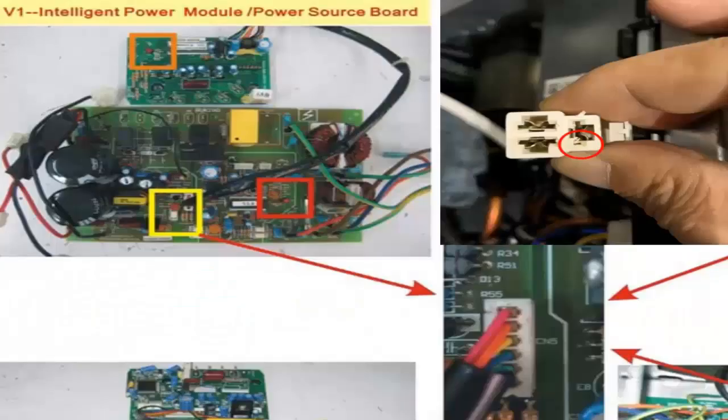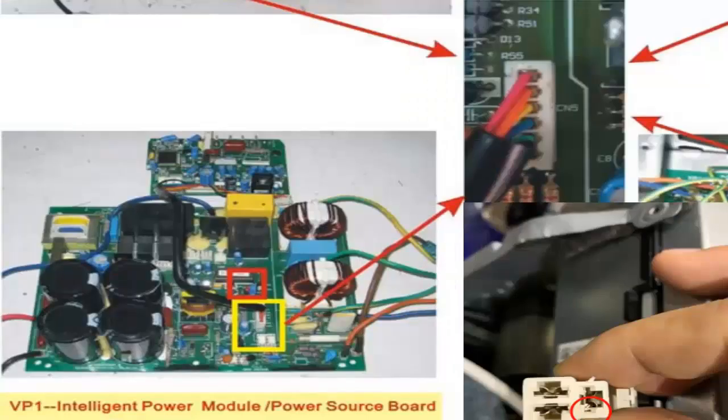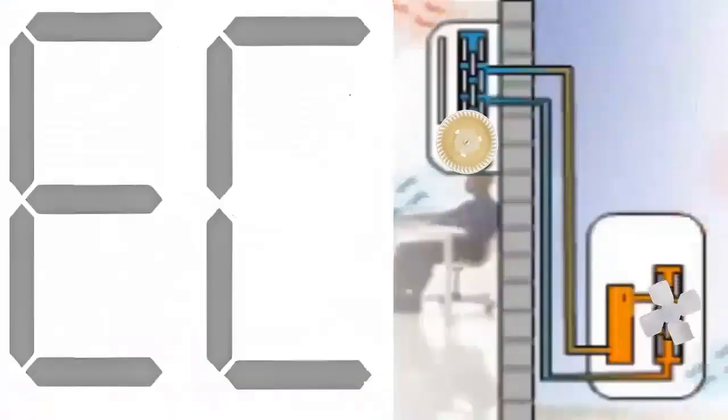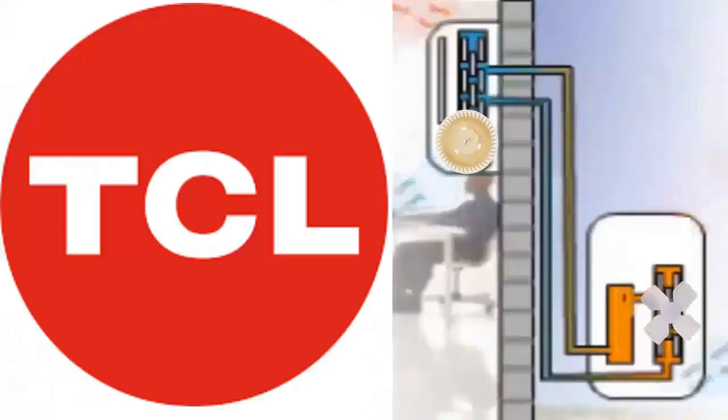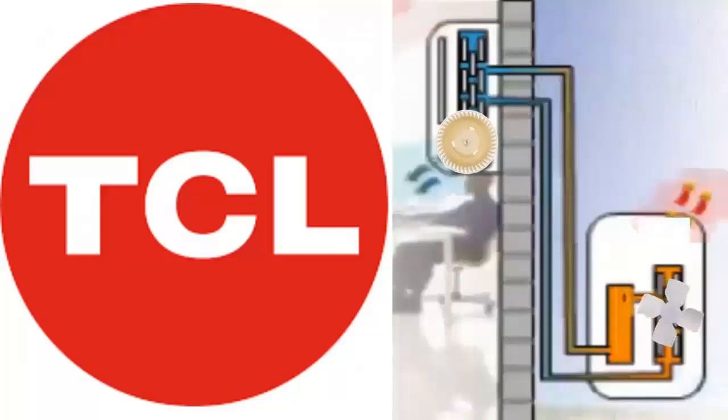5. Disconnect the connections, check their condition, clean the connections, and ensure there are no cut wires. Also, check the condition of the wires that connect to each electronic module in the external unit. Reconnect and power on the unit to see if the error disappears.